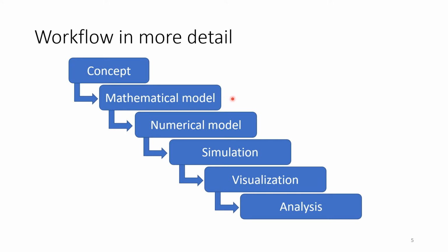This could, for example, if you want to model saltwater intrusion into a freshwater aquifer, be that density-driven flow is an important factor, because the saline water, so the seawater, will have a much higher density than the freshwater. So that is density-driven flow effects, and not many usual groundwater flow models will incorporate it. The ones we are using in this course will not be able to tackle that kind of problem.